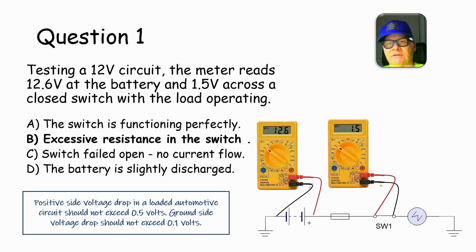Now you're going to have resistance at every connection. It doesn't matter if it's even a solder joint. You're going to lose some. I've actually seen wires that didn't have any breaks in them and weren't soldered or anything drop voltage, so that's another story.